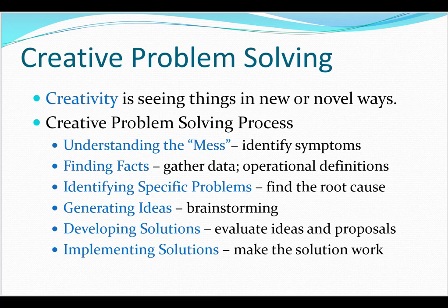It's a symptom of the actual problem. So we must understand all the symptoms, find all the facts, identify the actual specific problem, so do a root cause analysis, generate ideas, and that is best done by brainstorming, including people who are affected and who operate the process, and get them to brainstorm and generate ideas, develop solutions, and then implement those solutions.